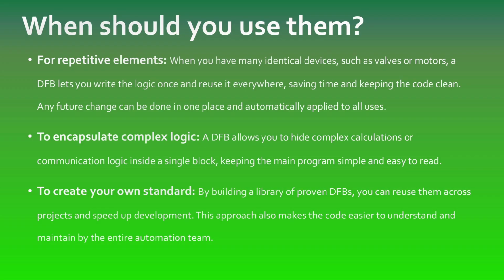To create your own standard, the best programmers have their own library of tried and tested DFBs. When you start a new project, you simply import your library, and 80% of the base work is already done. Furthermore, working this way ensures that the code is easily understood and diagnosable by any member of your automation team.